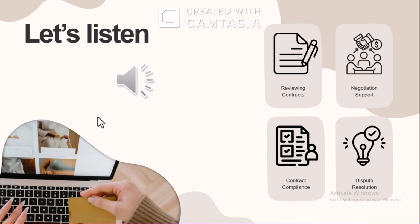Okay, done. But now the screen says feeder sensor error. That means the feeder sensor isn't detecting components properly. Did you check if the component reel is correctly installed? Oh, the reel is slightly misaligned. That can block the sensor's infrared beam. Adjust it. Done. But the error is still there.